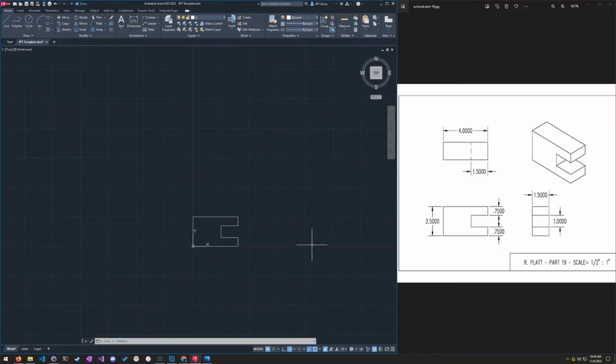So now I can either do the right side view or the top view. I'll do the top view now. That's just going to be a simple rectangle. So that's REC, enter. I'm going to hold my mouse here at the top of the part so I get the green square. Pull my mouse up so I get a green dotted line. And now I want the gap between the front view and the top view to be 4 inches. Remember, 4 inches, because on paper, the gap was 2 inches, but everything was scaled down by 1/2. So if I make it 4 and I scale this down later by half, the 4 becomes 2, the 2-inch gap that we had before.